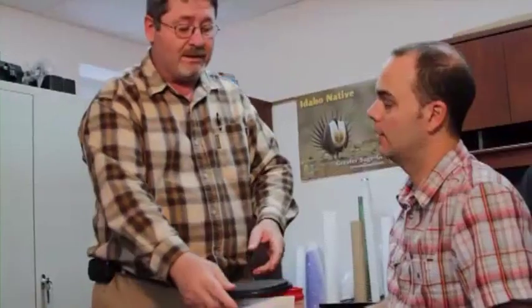There's all the collected batteries. Now these labels come out of the Accumulation Point Manager Handbook that we saw down at the Accumulation Point that Mark pointed out for us. This is an appendix to that handbook. You just print out that page and you follow the instructions on the page. Okay. Writing in the dates. The date that the first battery goes in here is this date. You add 6 months and write that date in, and that's your turn-in date. Oh, all right. So now we know how to properly dispose of a battery.